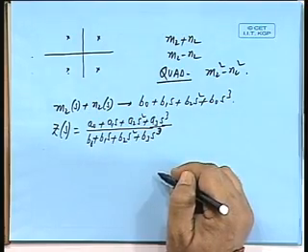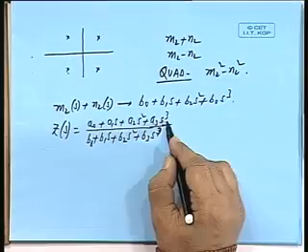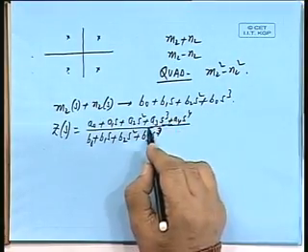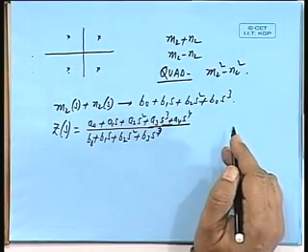The condition for a positive real function is that the powers of s should differ at the most by 1. Can I take a4 s to the power 4? See, by division there will be a free s term. That means some additive reactance element will come. It can be anything, so that becomes indeterminate. As I was telling you in the beginning, I can identify from that only the x corresponding to the minimum value.